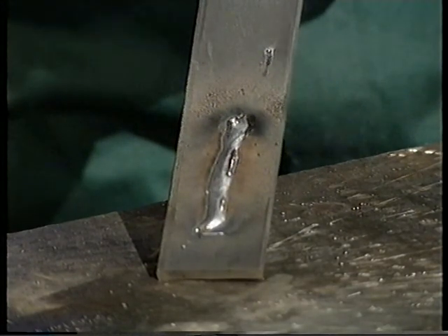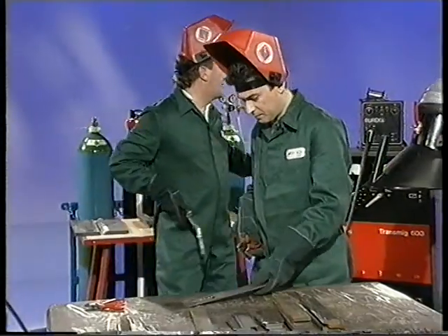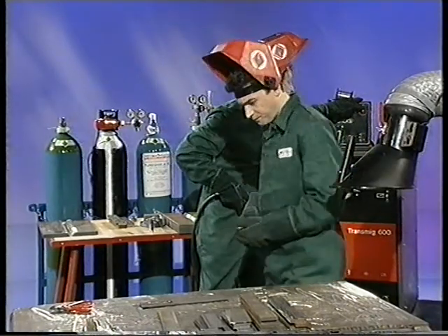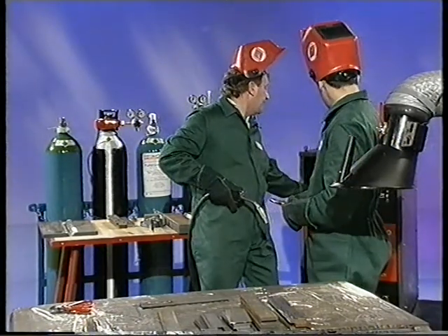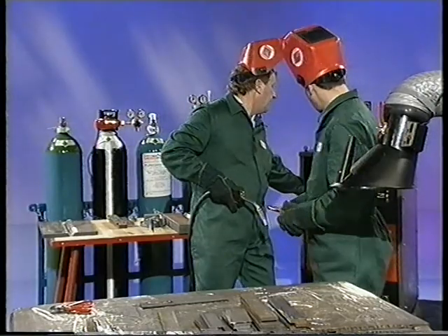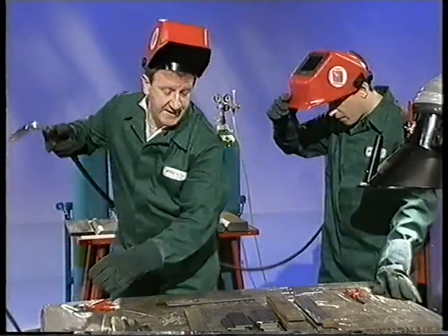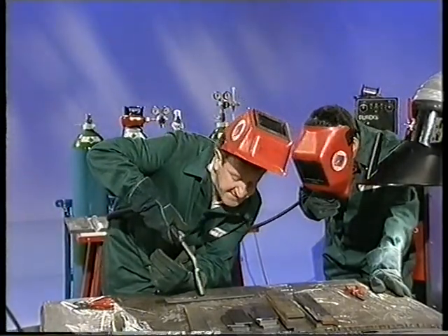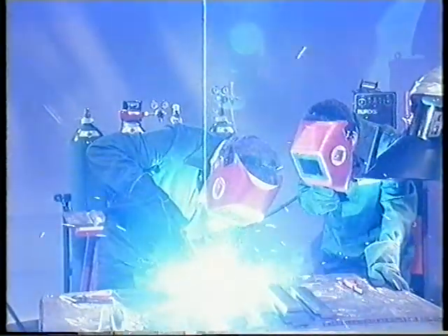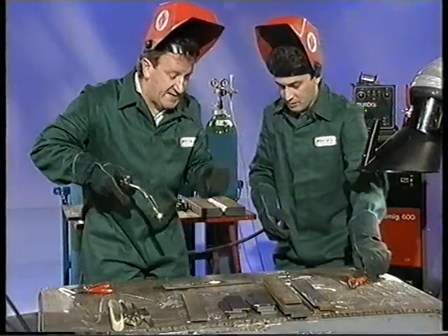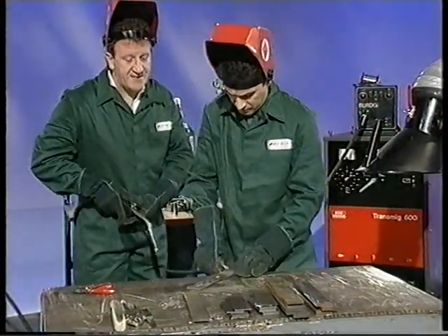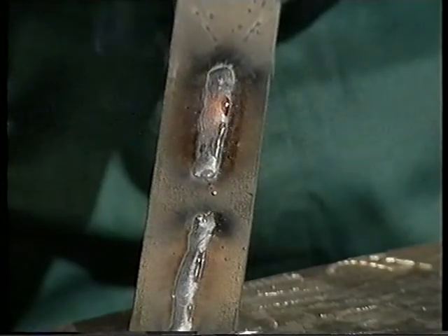Far more use is spray transfer, which we can do by increasing the wire feed speed again, in this case to maybe 12 meters a minute, and increasing the voltage even more. Let's see what sort of condition we have there. Just cut the end of the wire again. So mind your eyes. Well, altogether less spatter and less noise this time round. It sounds more in control. As you say, less spatter, less noise. And that's not too bad a spray welding condition. We can trim a little more to get better effects.